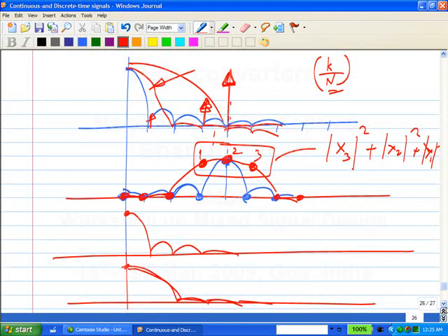So there is some modification, but that modification is described by this convolution. So there is more leakage from the neighboring bin, but much less leakage from faraway bins. Okay. The rectangular window, because it is 1, it looks like it is not modifying it, but because of the abruptness, it is modifying it a lot in some other sense. Okay.